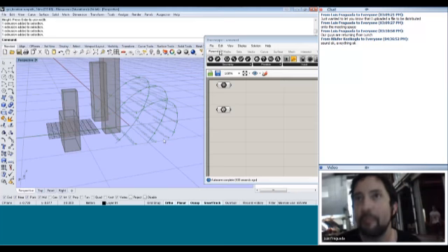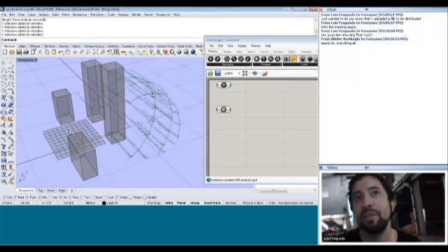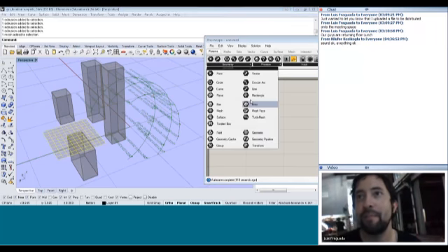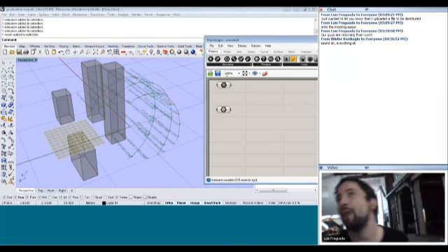Yeah, I'm now referencing the objects that I've drawn in Rhino. This one was a mesh, so that's why I used params, geometry, and mesh. And the other ones were B reps. That's why I used params, geometry, B rep. Yeah, when we're bringing things in from Rhino, we do this in params, geometry.